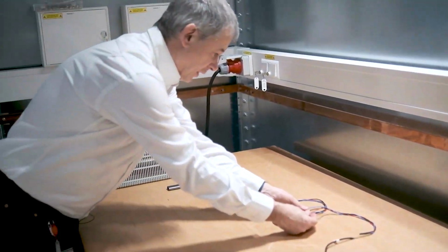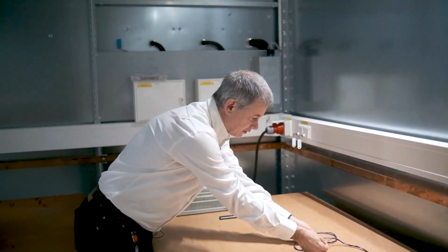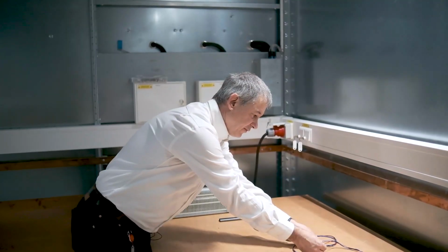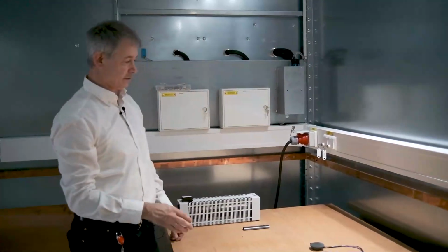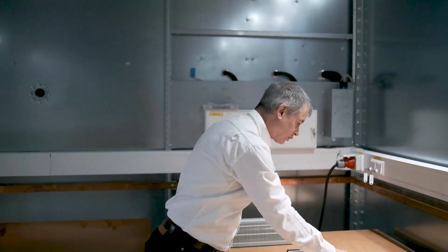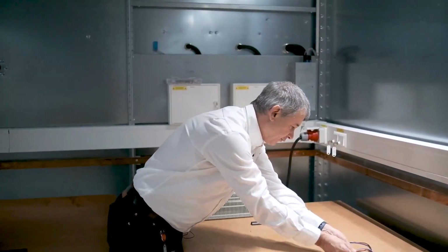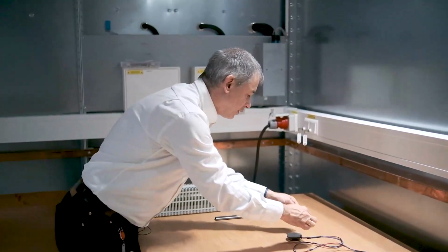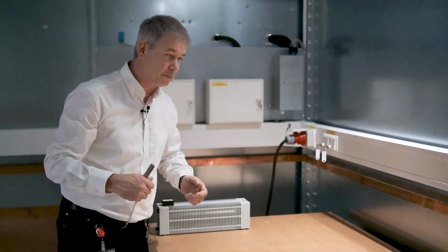At first, I will start by inserting a filter in the VCC line, a simple LC filter, trimmed to the 360 kilohertz of noise which is coming from there. And I will do it not far away from the system, but close to the system. But I think it's better to show it in the presentation.